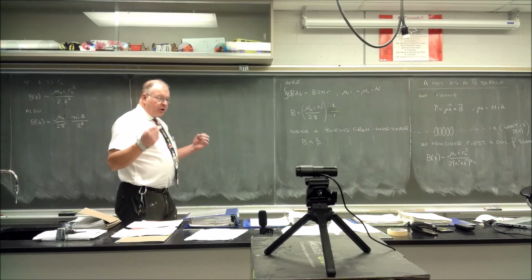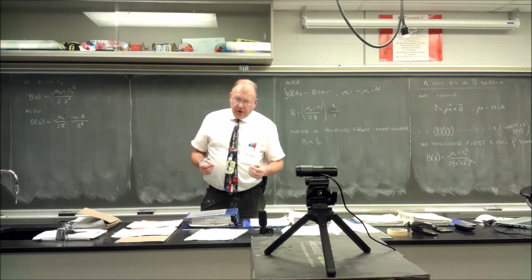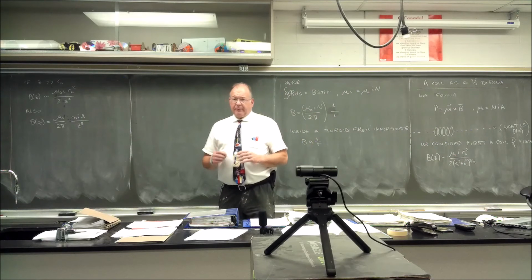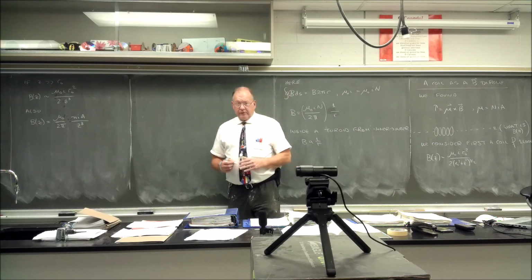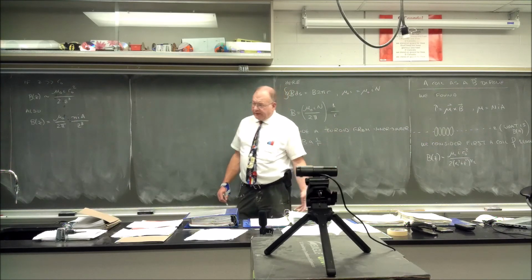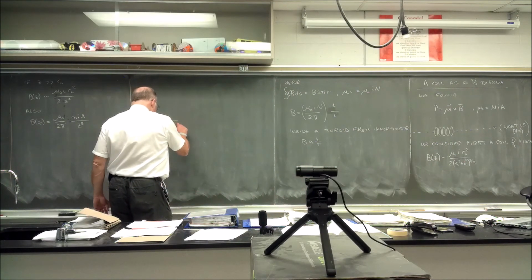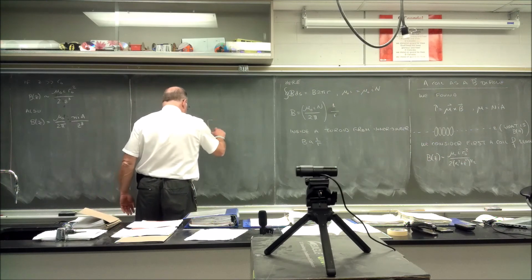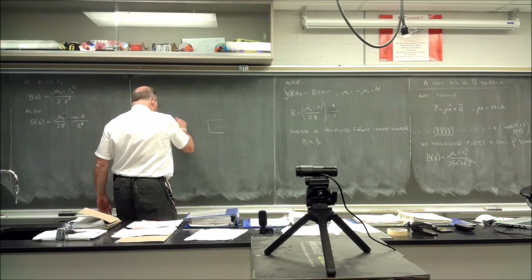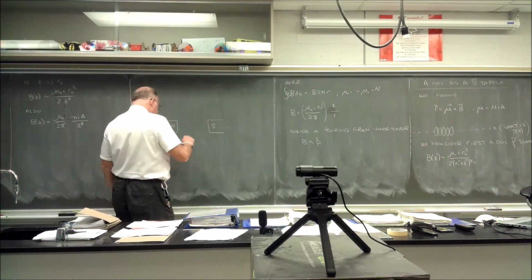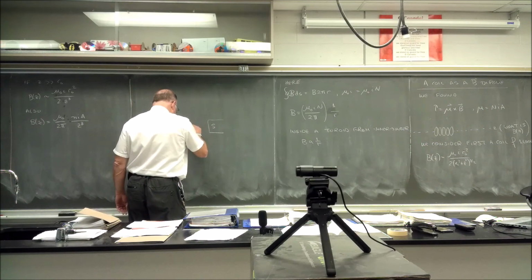If you have a current in a circuit and you wanted to measure the current or the voltage or whatever, and you want to use some kind of detection system, up until very recently, this is what we used. And I don't know, it's got to be 150 years old, something like that anyway. So what we do is, first we have a permanent magnet on either side. We'll have north, south, let's just arbitrarily choose them. Then we're going to put a coil here, like so, in which we'll put some wires around.